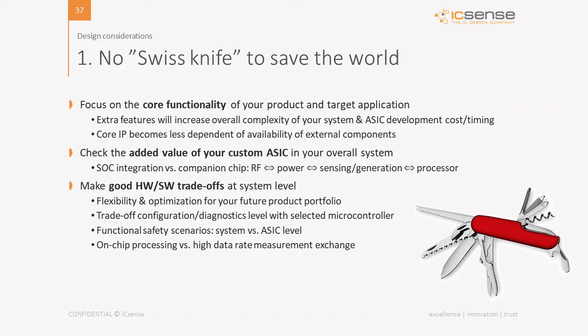Sometimes it's easier to integrate it on the ASIC, because by integrating a lot of external components and external flexibility, this can simplify the overall safety risk of your system and also simplify your qualification flow. It's very easy. Fewer components means you have fewer components to qualify. On the other hand, by integrating on chip, you can also define the right diagnostics that interface with your microcontroller.